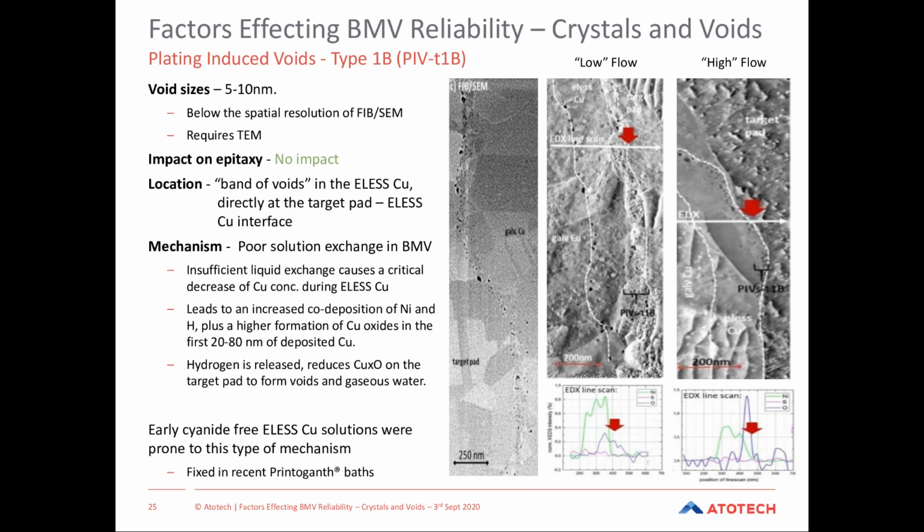The next one, again, a very similar mechanism, but we can associate this one with fluid dynamics occurring within the microvia itself. Again, no impact on bottom-up recrystallization. In this case, again, we start to see a band of voids directly at the interface between the target pad and the electrolysis layer. And there's two potentials that we could find this one to occur by.